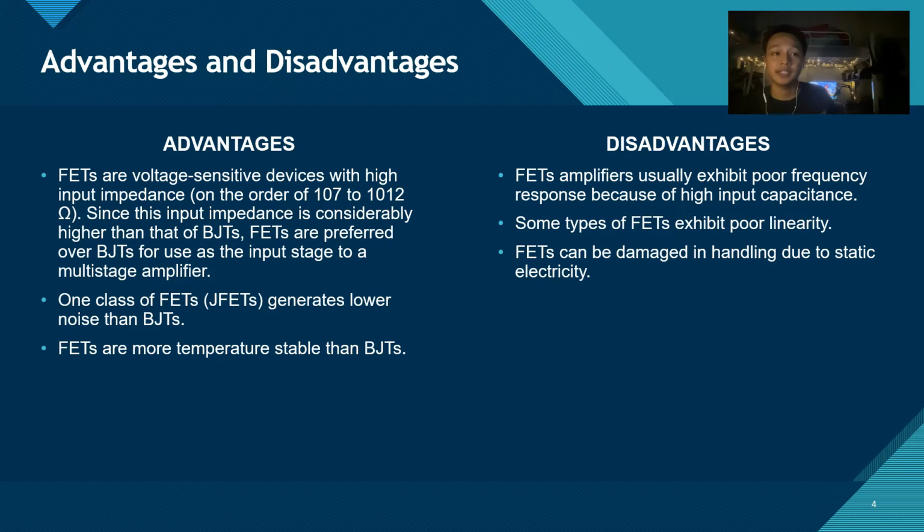Moving on to disadvantages. FET amplifiers usually exhibit poor frequency response because of high input capacitance. Next, some types of FET exhibit poor linearity. FETs can be damaged in handling due to static electricity.